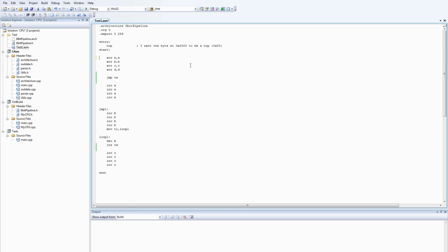So our first 16-bit value is going to be held in A and B. We'll do the same as before, and initialize that to 0. Our second value will be held in C and D, and we want to make that equal to 1. So similar to before, we'll load the address of loop 1 in, and now what is it we do?